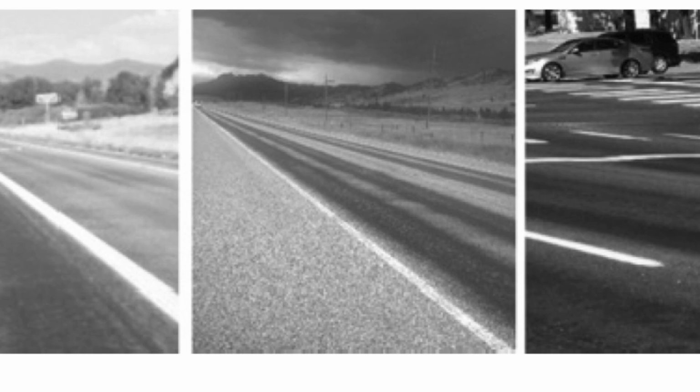Bleeding occurs when asphalt binder fills the aggregate voids during hot weather and then expands onto the pavement surface (Brown et al., 2009). This can be caused by one or a combination of the following: improper mix, such as high asphalt binder, too soft asphalt binder, low air voids, etc.; construction deficiencies, excessive tack or prime coat, etc.; environmental conditions, excessively hot weather, etc.; traffic effects, high traffic volumes, etc.